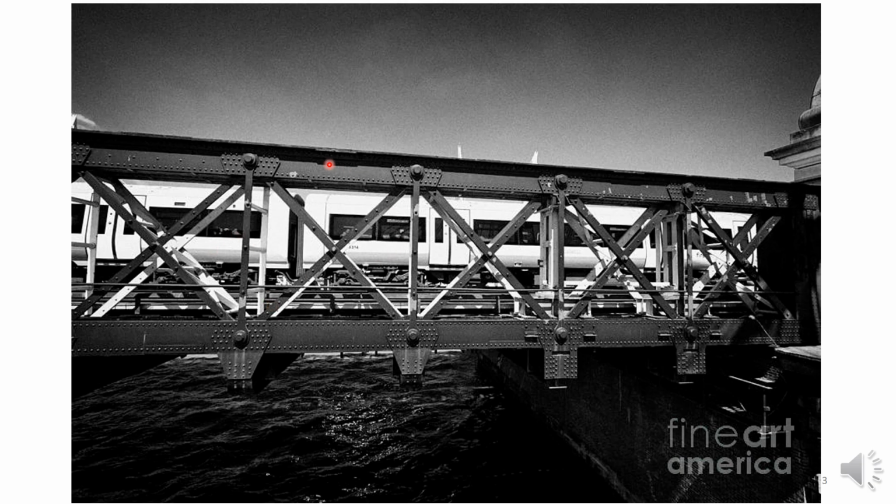This is a typical truss that is used in this case as a bridge structure. These trusses are very useful for narrow bridges, and in this case we see a rail bridge here. So it's quite common in rail bridges, temporary bridges also, which are usually narrow structures. And you can see that the members are steel members, and they are connected to each other by hinge joints.